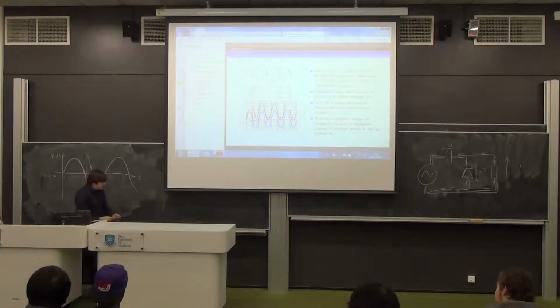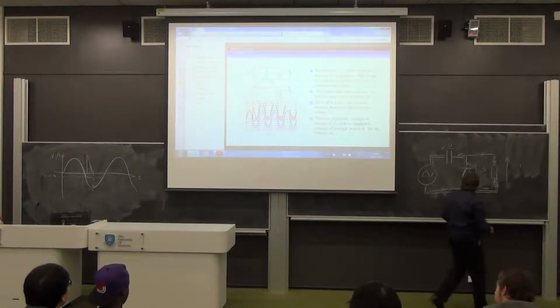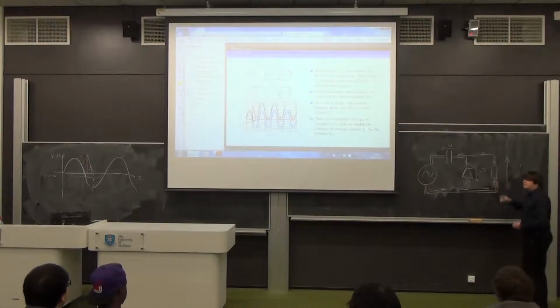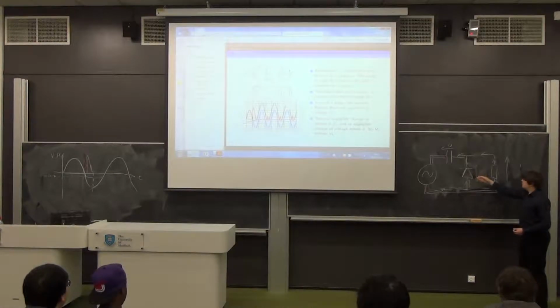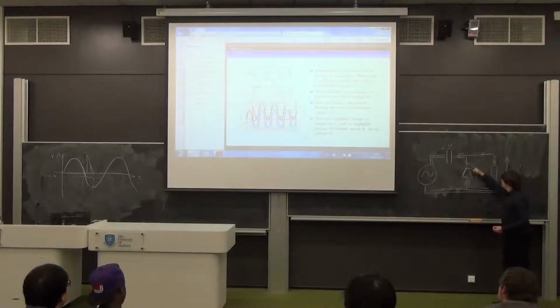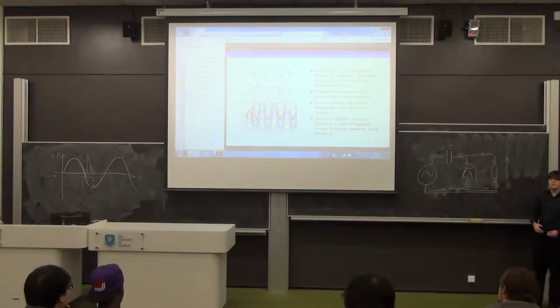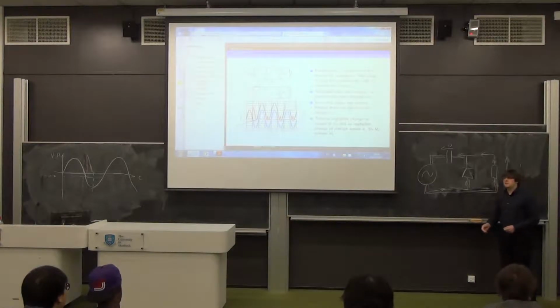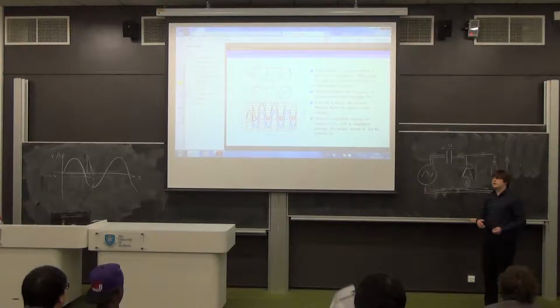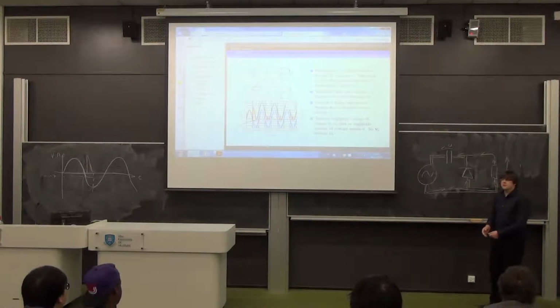This means that the situation on the diode is now that it won't be forward biased anymore. It will actually fall away from 0.7 and the diode will switch off. And when it does that, the current ceases. Strictly speaking, what happens is the current ceases and therefore the diode turns off. It's not a case of take away the voltage and the diode stops conducting. It's take away the current and the voltage will go away. And all at the same time, we say the diode stops conducting.